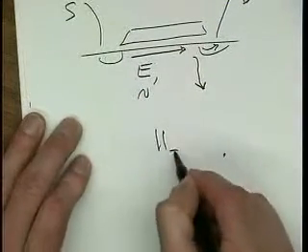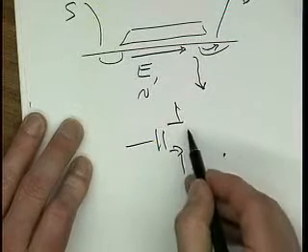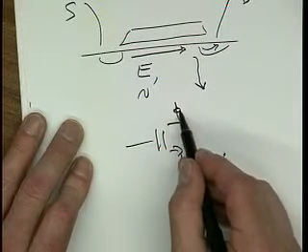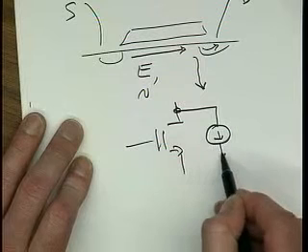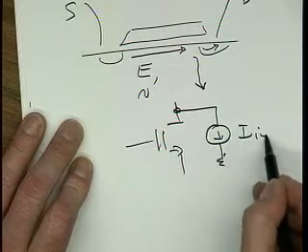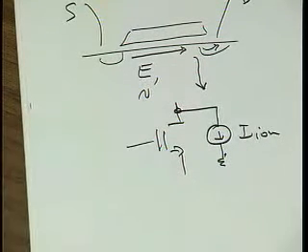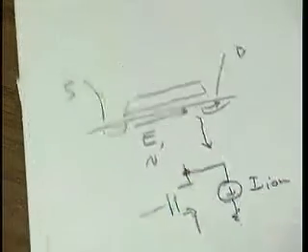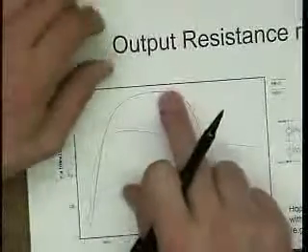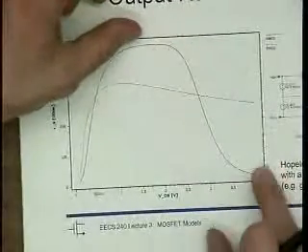It's like if we had the transistor and we have its normal ID, but then in addition we now have an additional impact ionization current that runs into the substrate. And as we crank up VDS, this one gets bigger and bigger. And it's particularly a problem for the electrons because somehow they have more energy. Okay. So that's the reason why, after things sort of get so good, suddenly they get bad again.